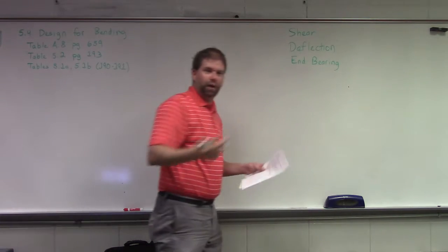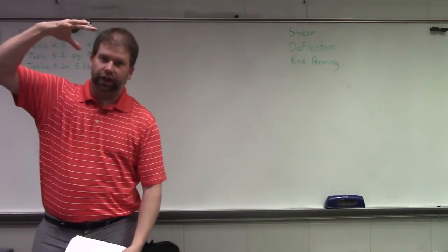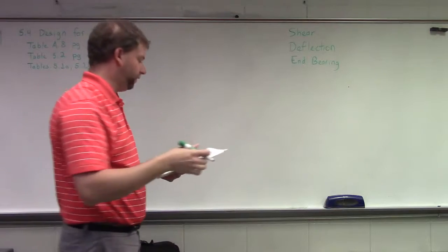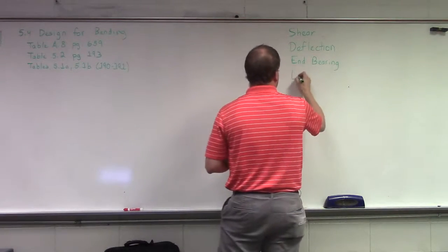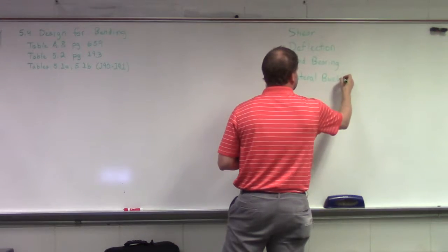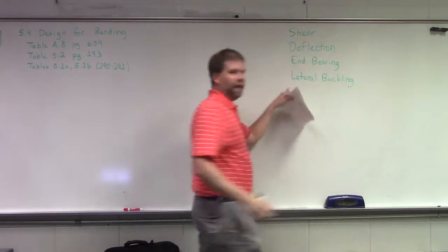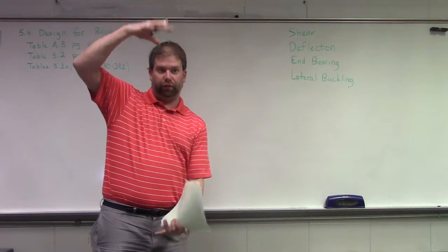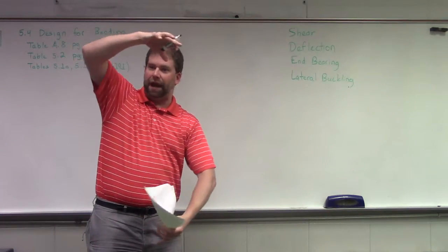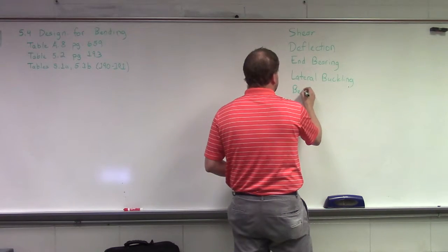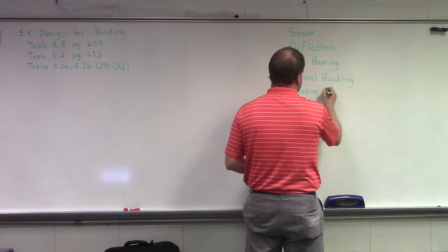We're interested in end bearing: as we apply a load to it, what's happening to the ends of the system? We're interested in lateral buckling, which we won't look at with the structural lumber. That's what we look at with the steel: as we compress this thing and it starts trying to bend, what's happening to it? But we are going to look at bending stress of beams.